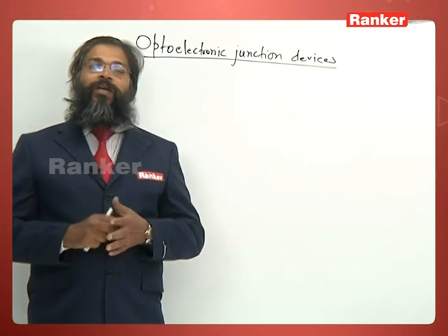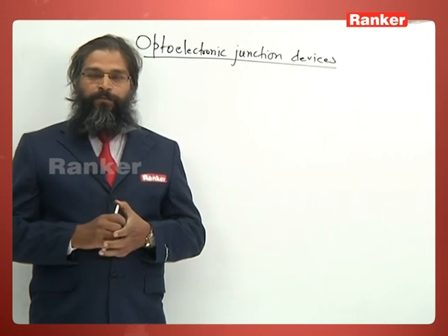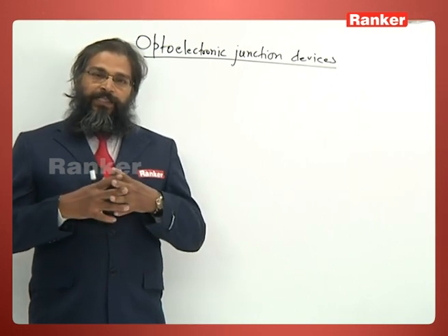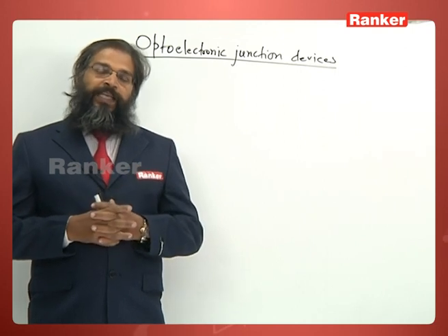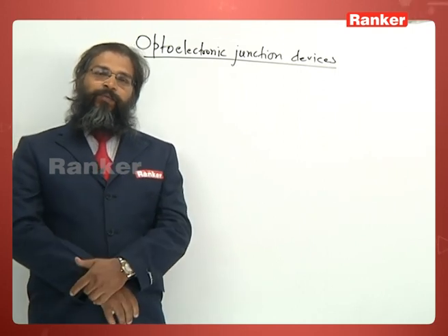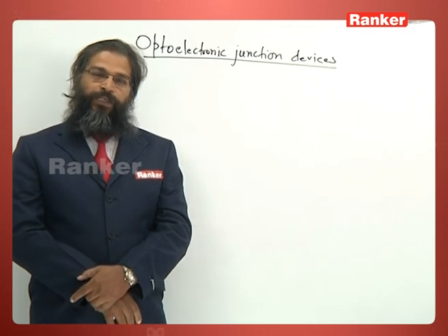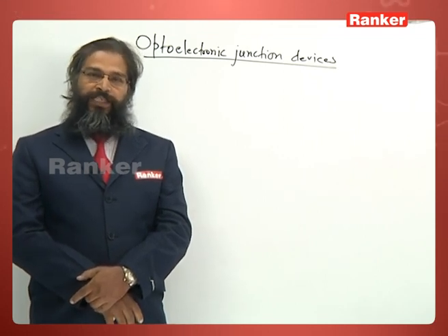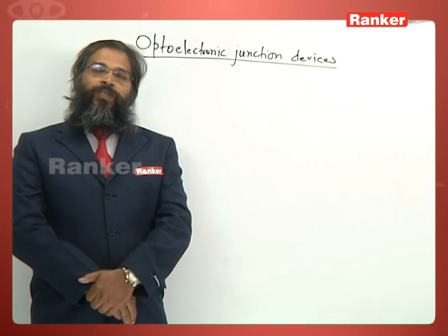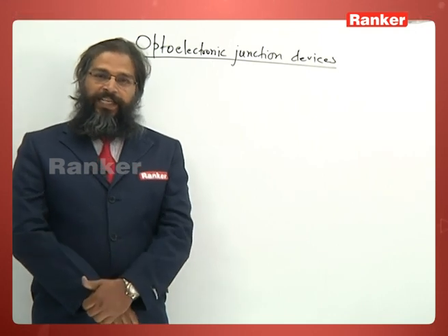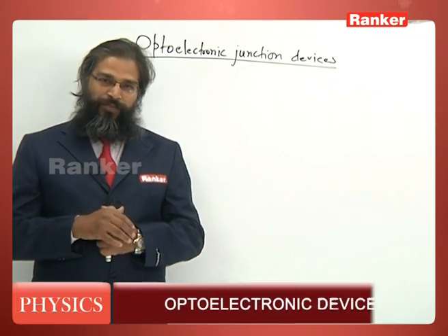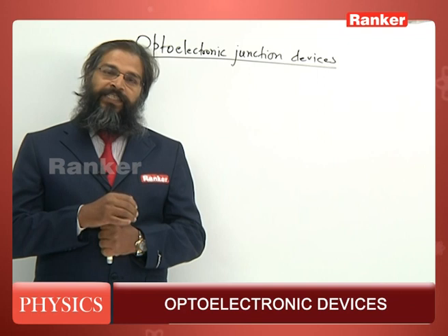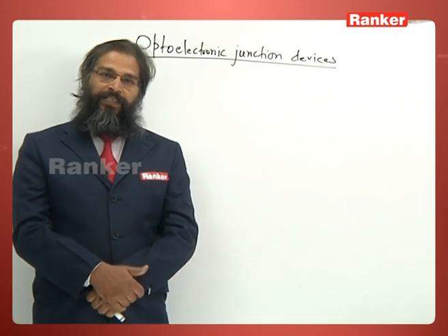These electron hole pairs are created, and the energy required for creating them in the case of silicon was nearly 1.1 electron volt, and for germanium it was 0.3 electron volts. So, the minority charge carriers were created by the energy acquired from thermal motions, thermal energies we say. That is the energy which is in the infrared region.